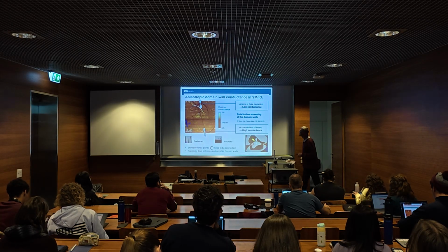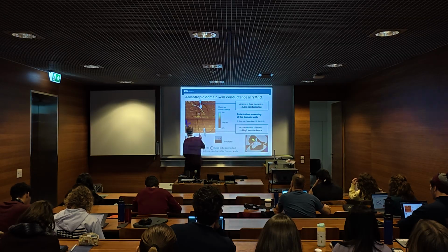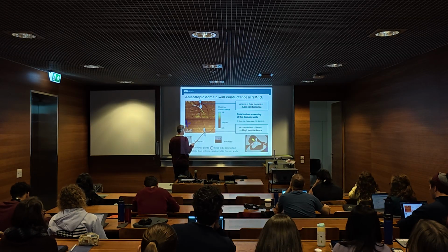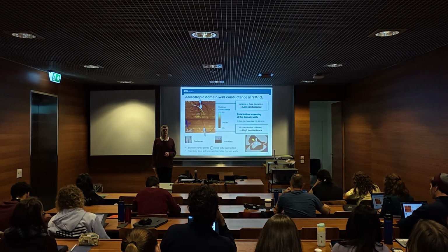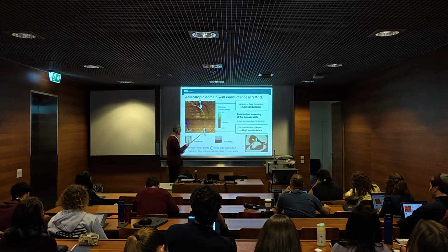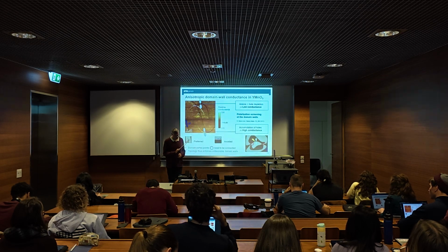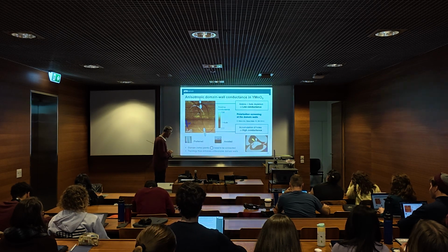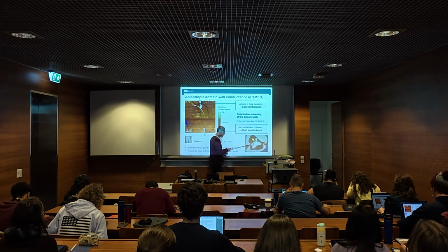Here's another one where you can see domain walls, and depending on the direction of the ferroelectric domain wall, you can have lower or higher conductance in the wall. So this is even more intricate. It's not only that the wall can be a conductor, a wall can also be an insulator depending on the orientation of the wall, which is another interesting functionality you can play with. It's this hexagonal manganite pattern,